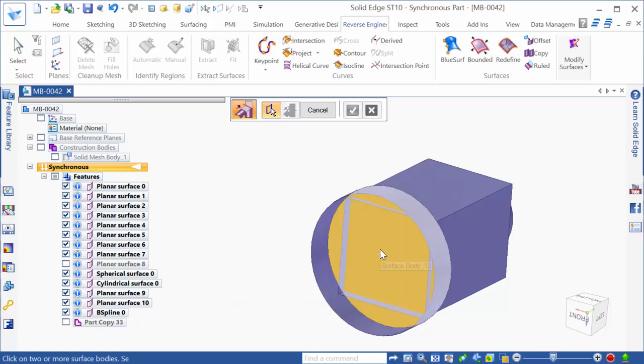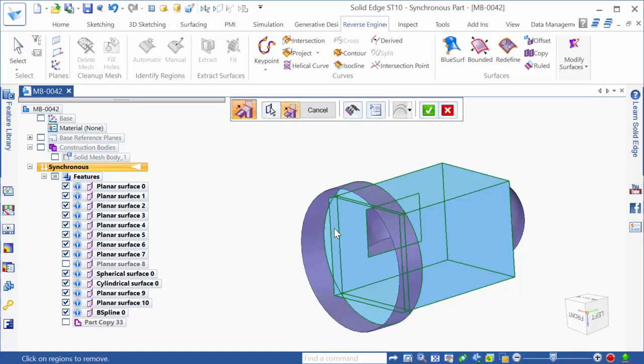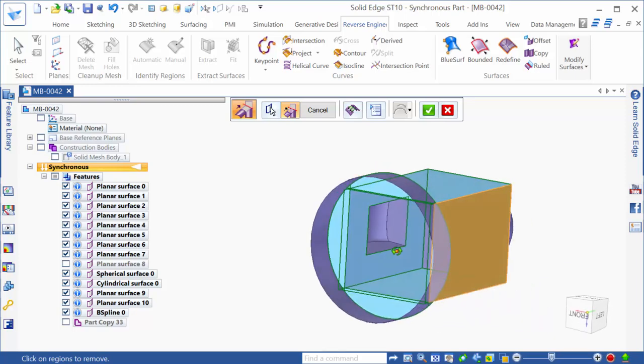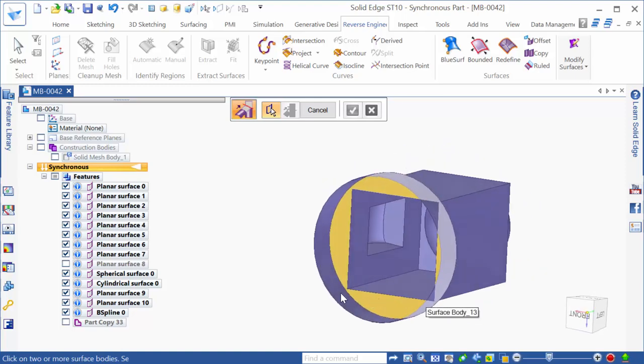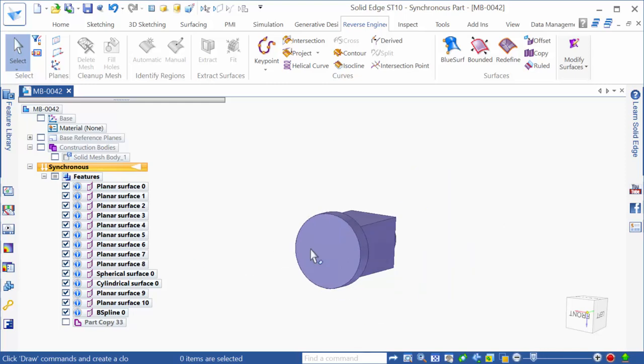It's going to turn off the bottom face, or the bottom surface, and then you select the bottom and then the 4 corners, so that you can go through and you can trim away the excess, as well as this area right here. So you have one solid surface that's all trimmed to each other and hollowed out in the middle.